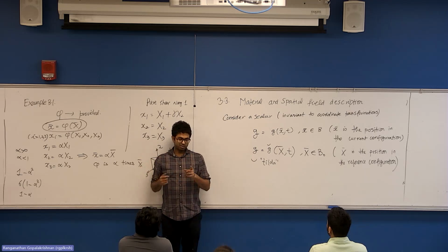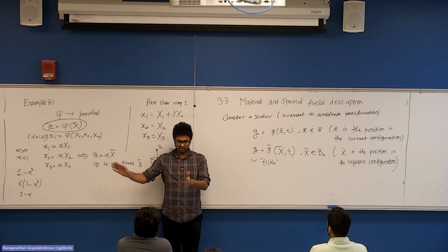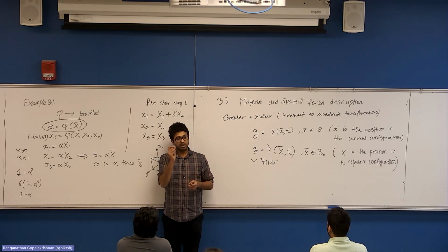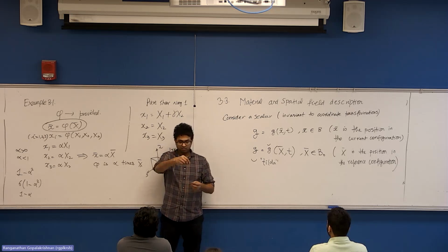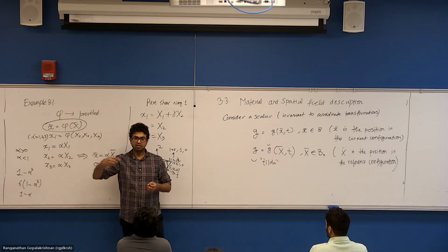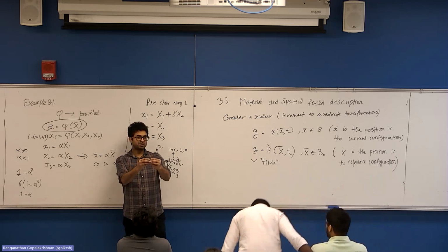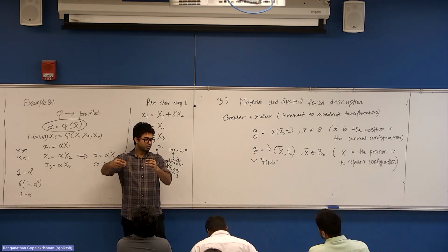Fluid mechanics example: if I stick a probe that reads out the velocity at a given point, I am only interested in the velocity at that point. In 1 second, in 1 instant, fluid molecules come. I read their velocity, they are gone. I don't care about them. I care only about that point. If you do a tracer, drop a dye, watch the streak of dye go through your fluid, that becomes Lagrangian, or tracking. I'm taking a tiny parcel of fluid and watching how that parcel is distributed.